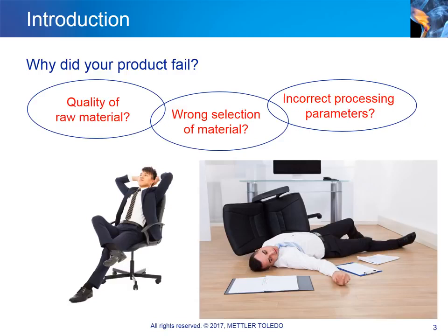Only then can proper materials be selected and the necessary production processes optimized. Typical examples include the identification of polymers by their glass transition temperature, crystallization and melting temperatures, composition analysis, and decomposition behavior, or the determination of mechanical parameters, such as the coefficient of thermal expansion or the modulus.